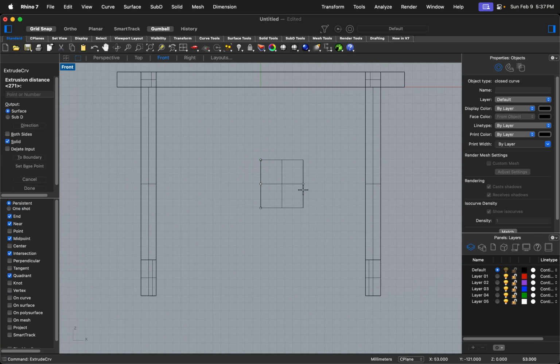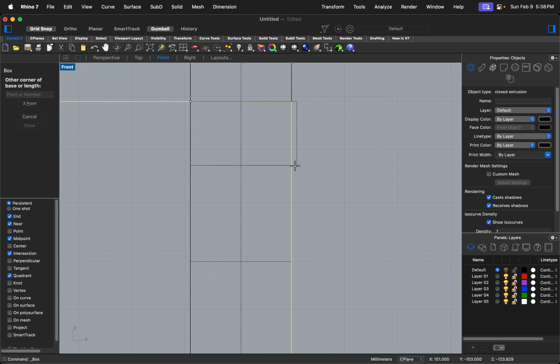So once you get the center rail done, you notice that if you cut the center rail like this, the mortise won't work because the tenon doesn't have a stopper here. So what I'm going to do is create a box again. Yes, we're going to use the box again. Go to the box. So create a little offcut here. Keep it approximately 10 mm, 9 to 10 mm. And I'm going to put the stopper in.